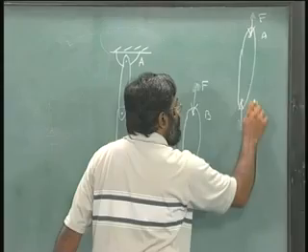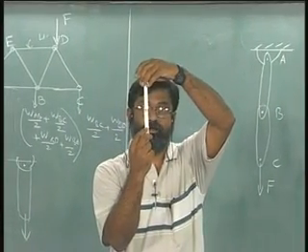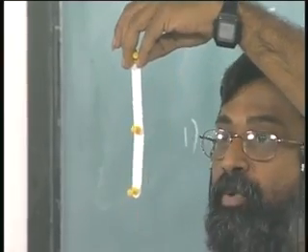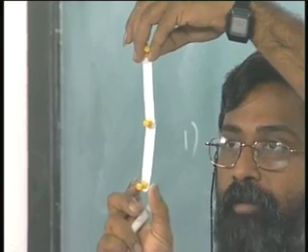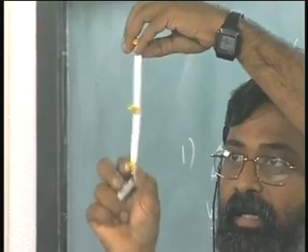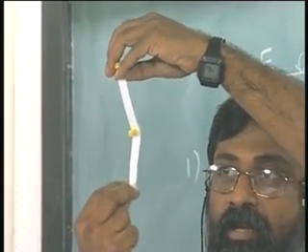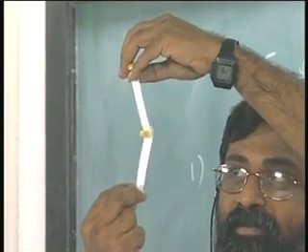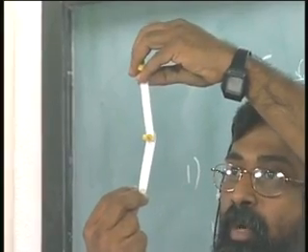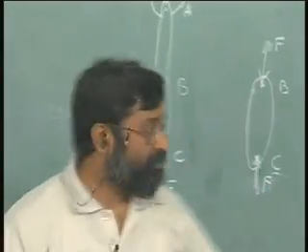But if you notice carefully, if I apply that kind of force, it is perfectly alright as long as it is along the axis of both of them, but if I apply it a little inclined way, it starts to, right, you can see it just goes. As long as it is completely axial there is no problem, but even a small angle is enough for it to collapse, or in other words a small angle is enough for it to become a mechanism, okay. But how is it that I am able to solve this problem?